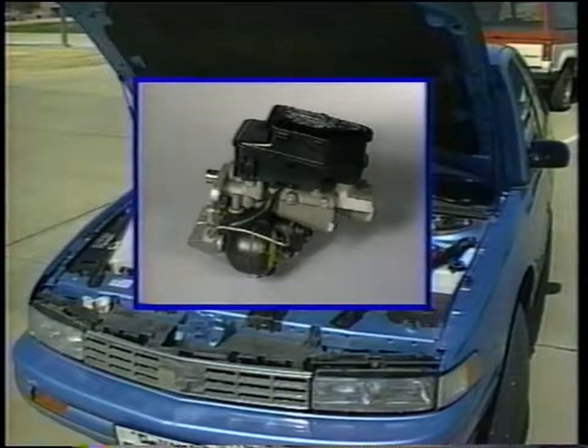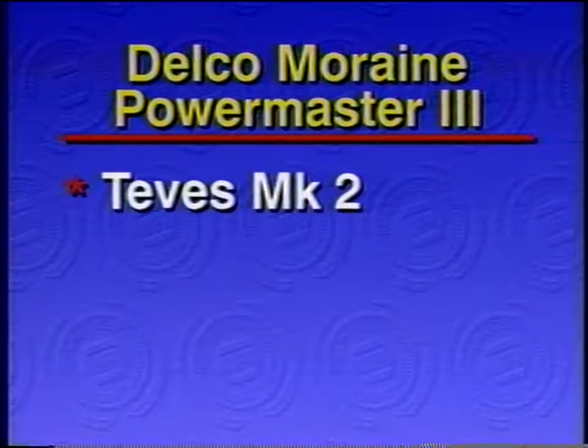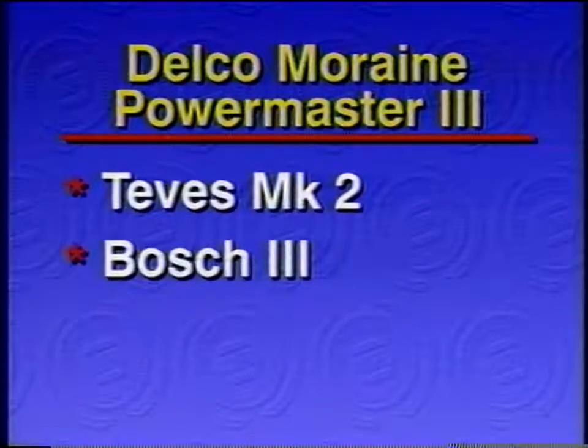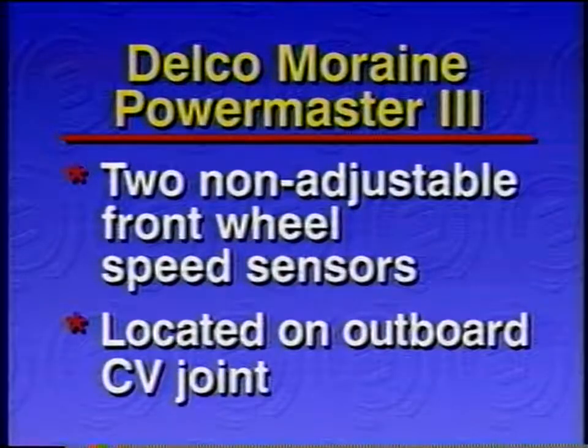It uses a high-pressure pump and an accumulator for power assist as well as for anti-lock braking. It's functionally similar to other integral ABS systems, such as the Teves Mark II, Bosch 3, and Bendix 10 ABS systems. The PowerMaster 3 system has 4 wheel speed sensors.